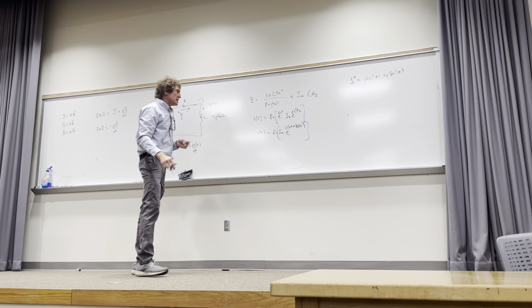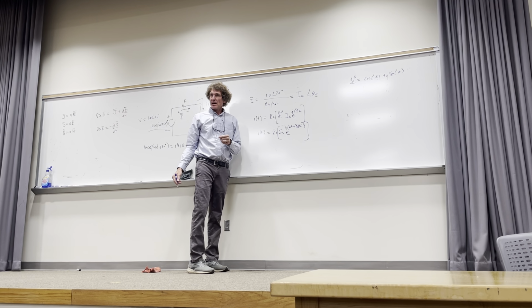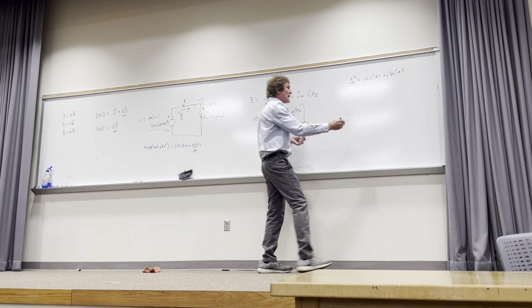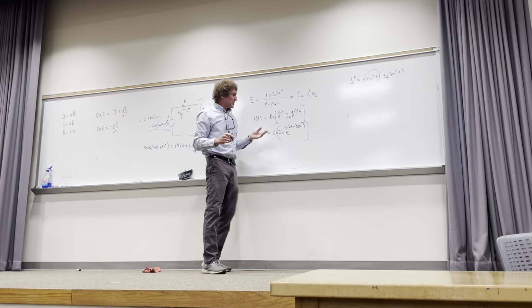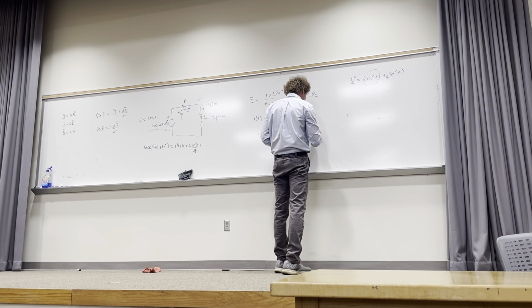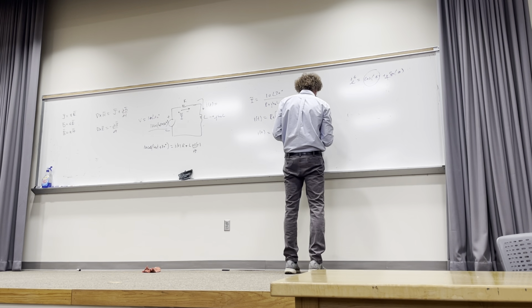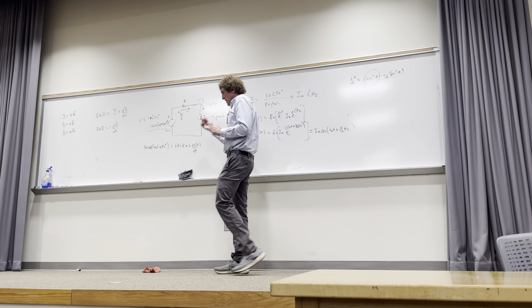In this case, my theta is really omega t plus the angle, isn't it, class? The real part of that is just the cosine. When you see a j, that's imaginary. So when I take just the real part of this, I get Im right here, and then I have cosine of omega naught t plus this phase angle that has to do with the current. And now I've solved for I of t here.